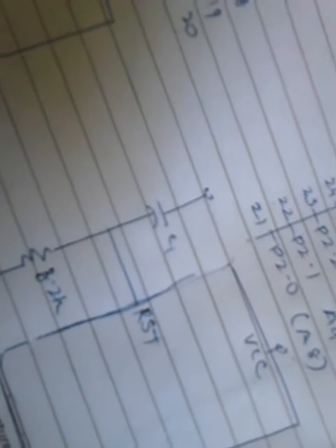Basically, 8051 has 40 pins. Pin 1 to pin 8 is port 1, which is an 8-bit bidirectional I/O port with internal pull-ups. Pin 9 is the reset. Its circuit consists of a capacitor and a resistor. When the capacitor is fully charged, it blocks the DC and resets the 8051.